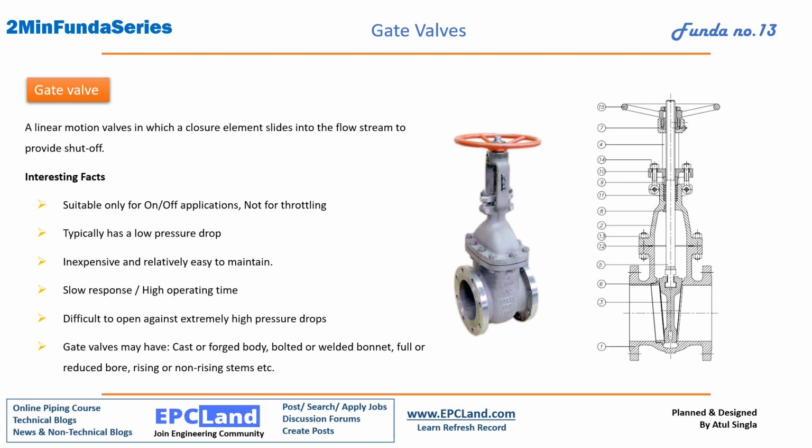Inexpensive, relatively easy to maintain. Okay, its manufacturing is very easy, it's simple to manufacture, and it can be used at many places. Slow response, high operating time. We have to rotate it and the slider will go down and obstruct, so it is a little bit time taking, but it's very commonly used. Difficult to open against extremely high pressure drops. Okay, this is another drawback.